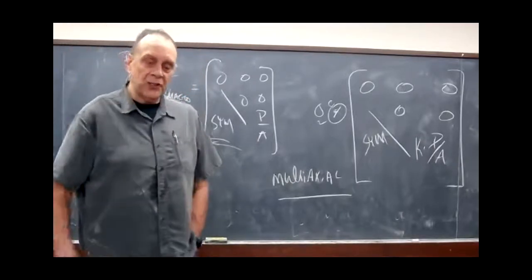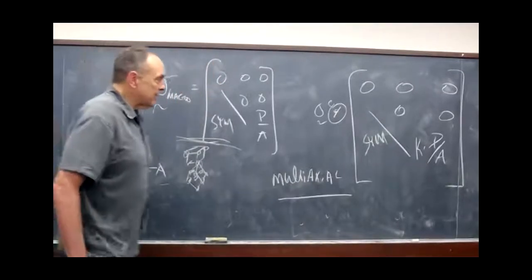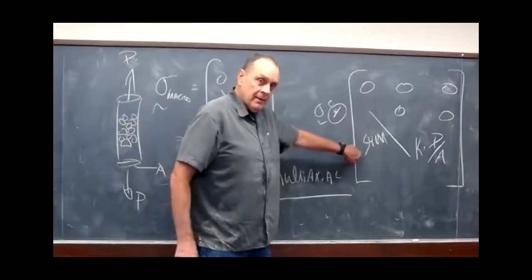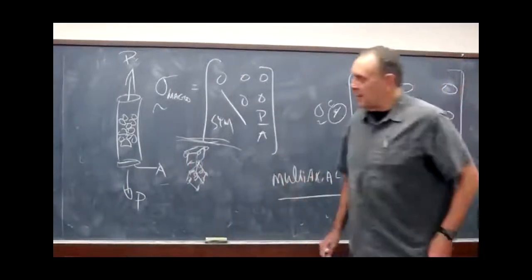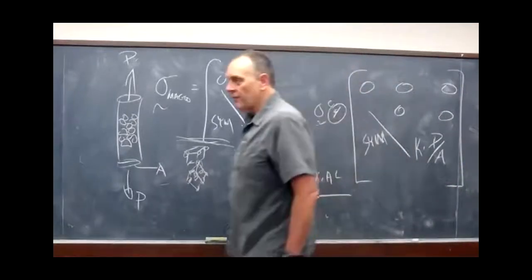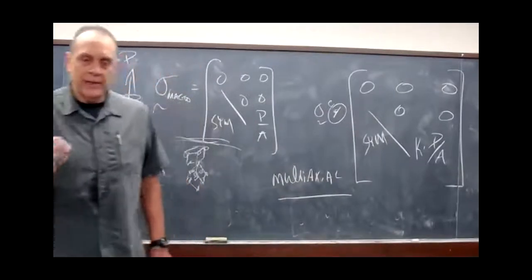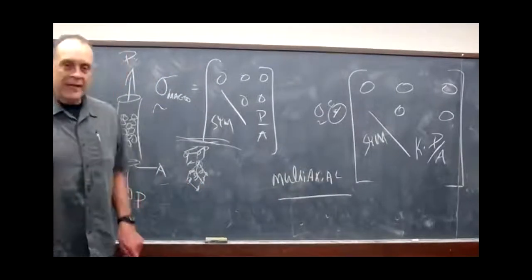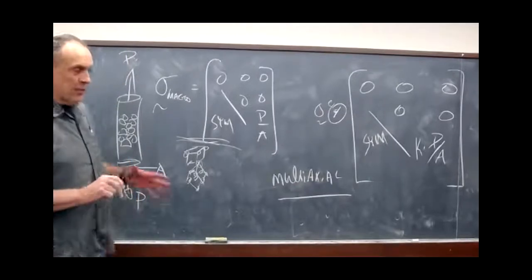It will calculate the Schmid factor for every crystal. Now, Schmid factor assumes this. I just said it's not this. So if you guys are EBSD people, I want you to disable that button so that you never ever calculate a Schmid factor looking just at the orientations. You've got to have more than just the orientations.